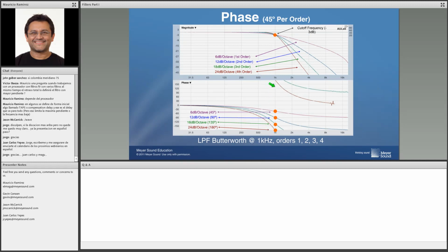So in other words, the range in time in 1K is the time period of 1K, is one cycle of 1K, 1 millisecond. So this express 1 millisecond, this express 2 millisecond at 500 Hertz, this is 4 millisecond at 250, this is 0.5 millisecond in 2K, this is 0.25 millisecond in 4K. So here we have 4 different orders in this low pass, and this low pass is Butterworth with the cutoff at 1K and is order 1, 2, 3, 4.